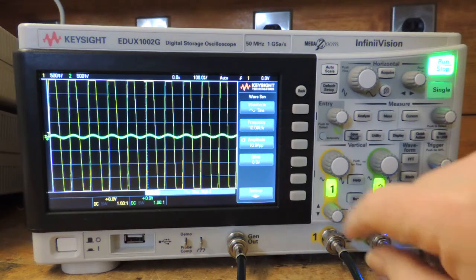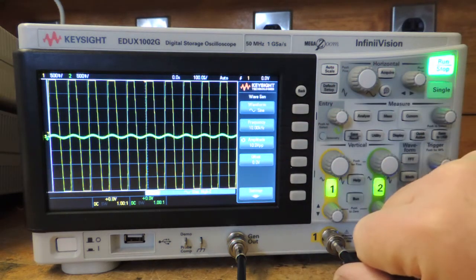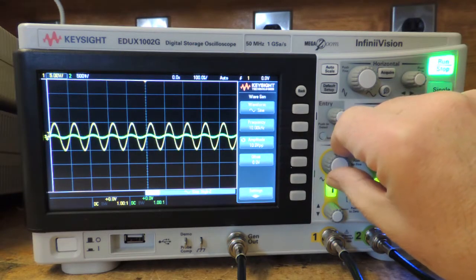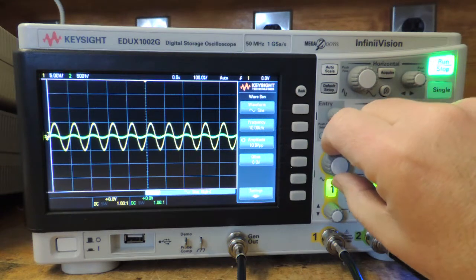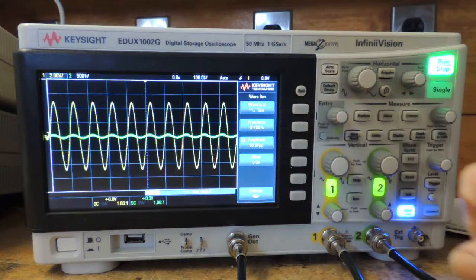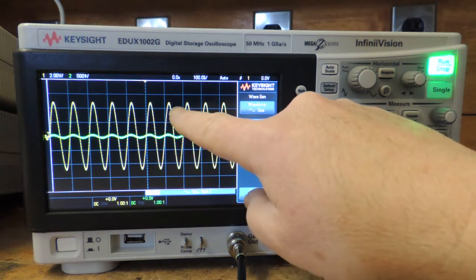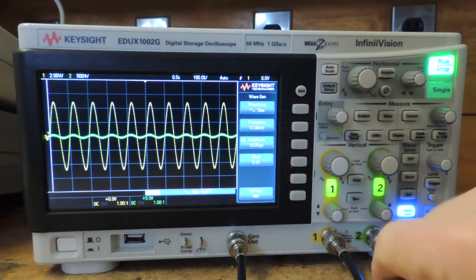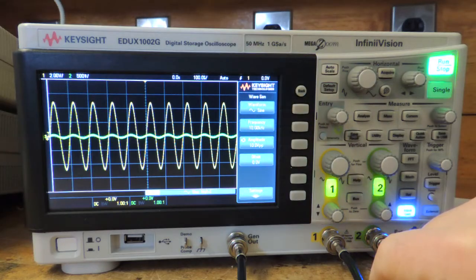So the next thing I need to do is take a look at channel 1. I can see the waveform goes off the screen, so I'm going to adjust my vertical control. I don't want it so small I can't figure out what it's saying, and I don't want it going off the screen. So in this case, for 10 volts peak to peak, if I put it on 2 volts per division, I can see it goes up 2.5 divisions. So that's 5 volts up, 5 volts down, that's 10 volts peak to peak. Now I know all my settings are correct, and the oscilloscope's displaying the correct readings for me.